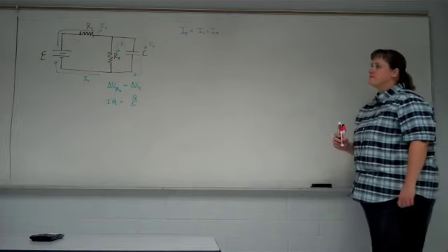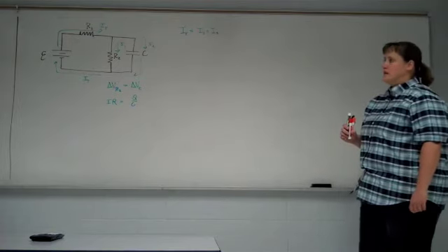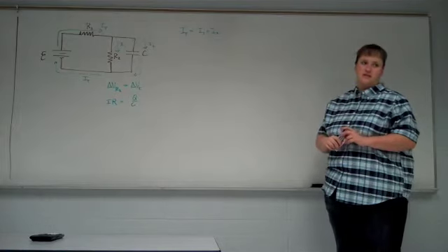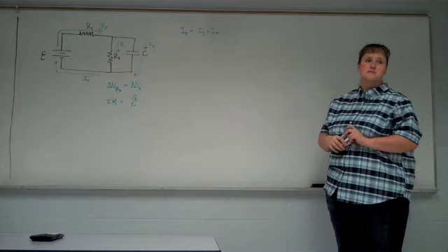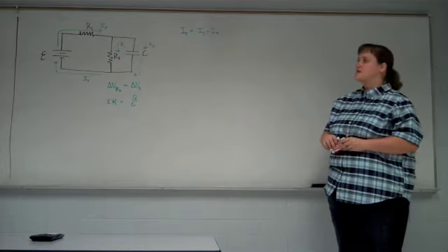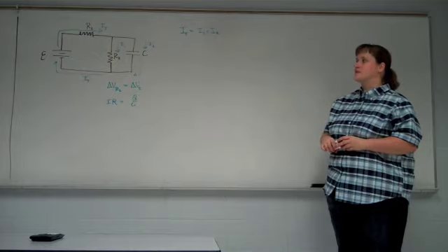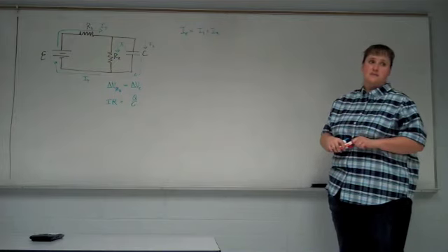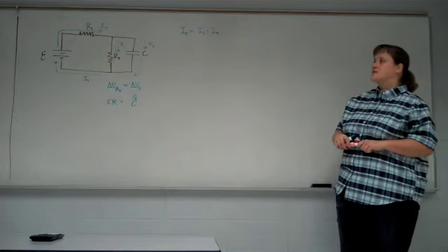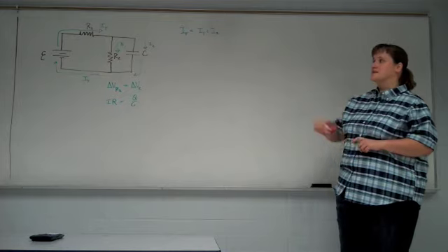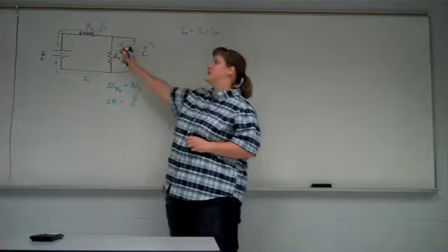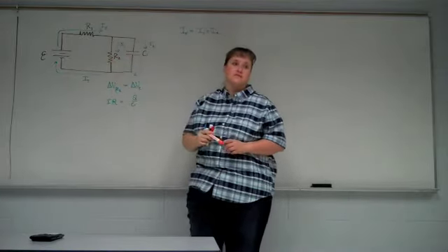Okay. Because of the capacitor, the whole thing just stops. No, the current won't stop, but the changing of the current will stop. There's a maximum voltage that capacitor can reach. Once the capacitor has reached that maximum voltage, then the current will no longer change in this case. The capacitor can't stop the current though, because there's another branch for current to flow through. Current has the option of coming this way.